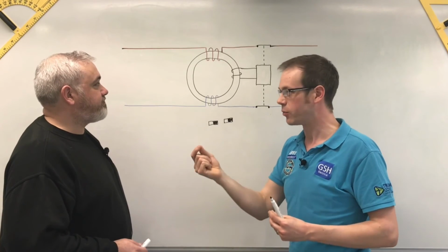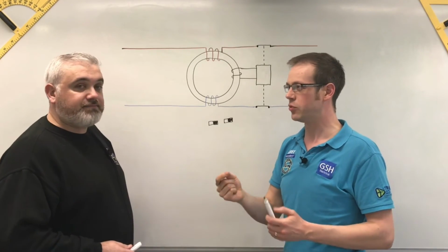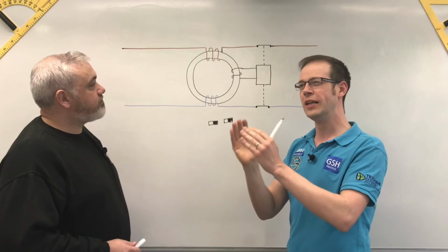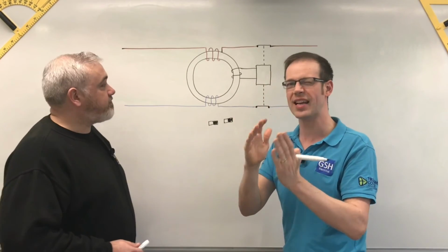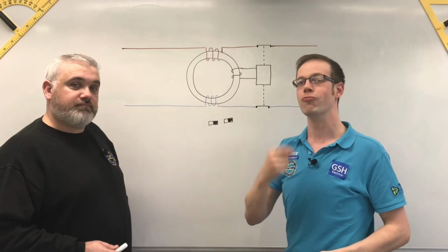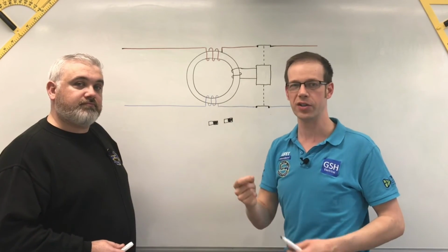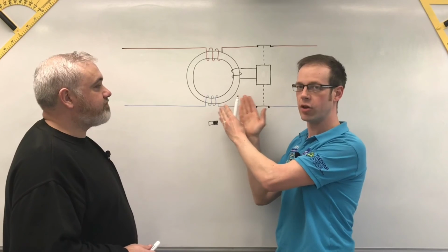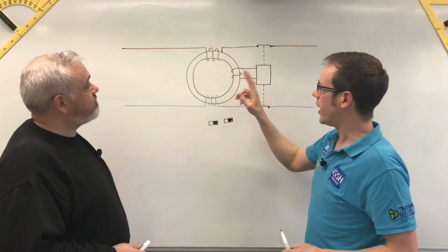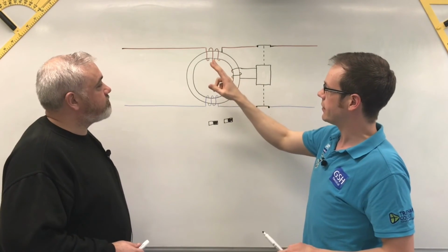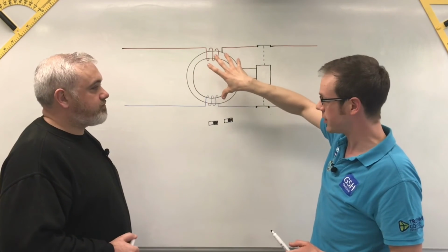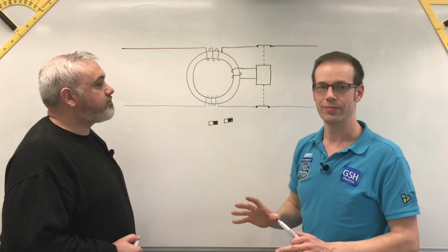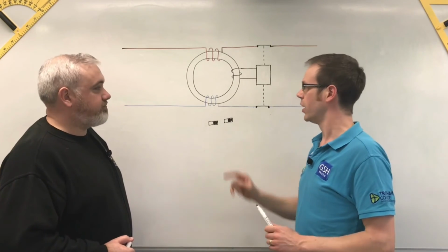It does. It's that expression again, being saturated, which is when in a magnetic core all the molecules end up lined up in one way. Okay, the technical term for what's happening here is remanence. If I use the word remanence, I just mean leftover magnetism in the core. So what we're looking at is, as the current is flowing, we end up with this iron core remaining slightly magnetized. And then if a fault occurs,